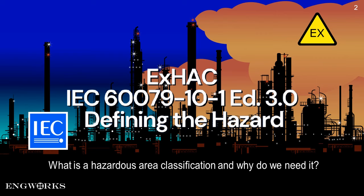A classification design describes the probability and the location where an explosion hazard will exist. It is used to specify explosion-rated electrical, mechanical, and instrumentation equipment. It also influences the material and wiring methods used to construct a facility, and, most importantly, it defines the safe work practices used in that facility.